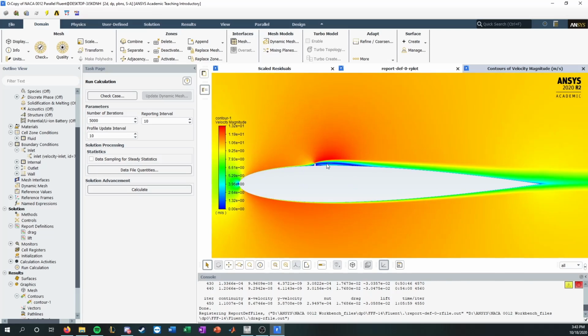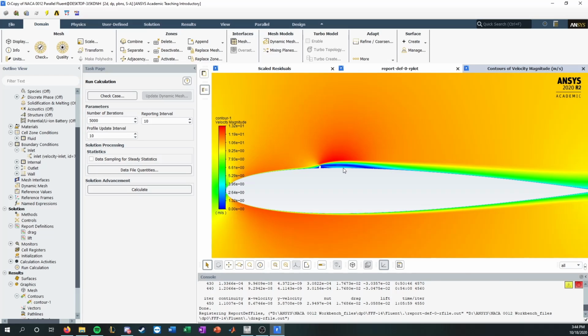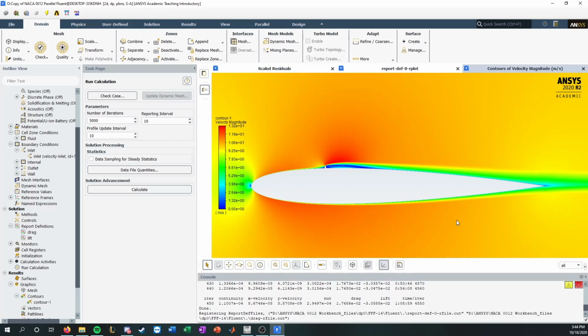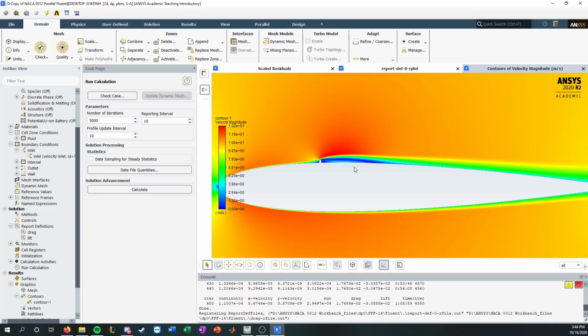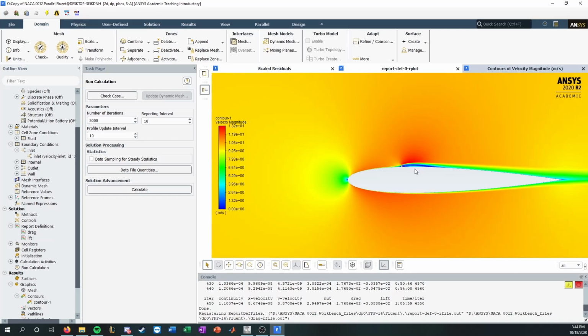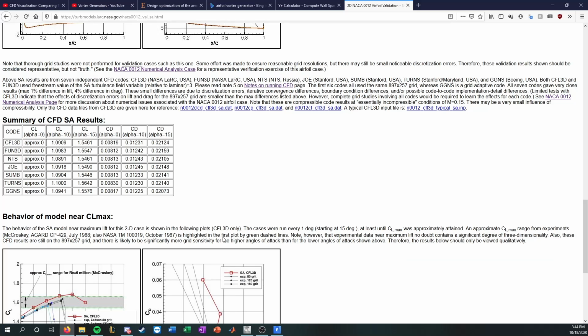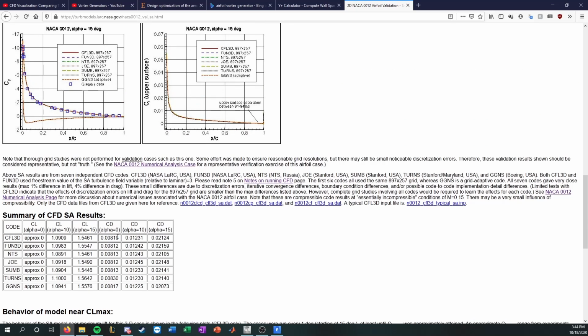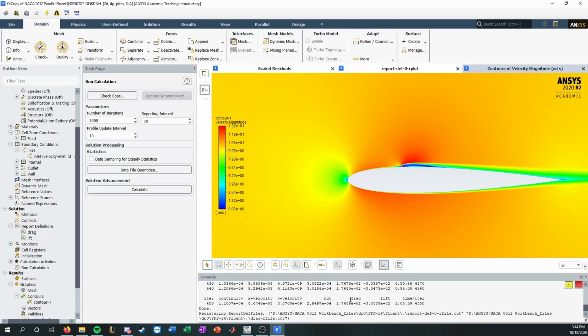So looking at the drag and lift, we have negative lift. As I said, negative lift corresponds to less velocity over the top. So at 0 degrees angle of attack, if the velocity on the top and bottom is the same, that means pressure is the same, that means lift is equal. But because we have less velocity because of separation, as V goes down, P goes up. So there's more pressure on the top than the bottom, meaning the net vector of Y force is down. Drag, because this is a vortex, because it's separation, you now have much more drag in the X direction. So comparing it to Spalart-Allmaras, which is what I compared to previously, and I matched it perfectly, you will now have much worse drag and lift.